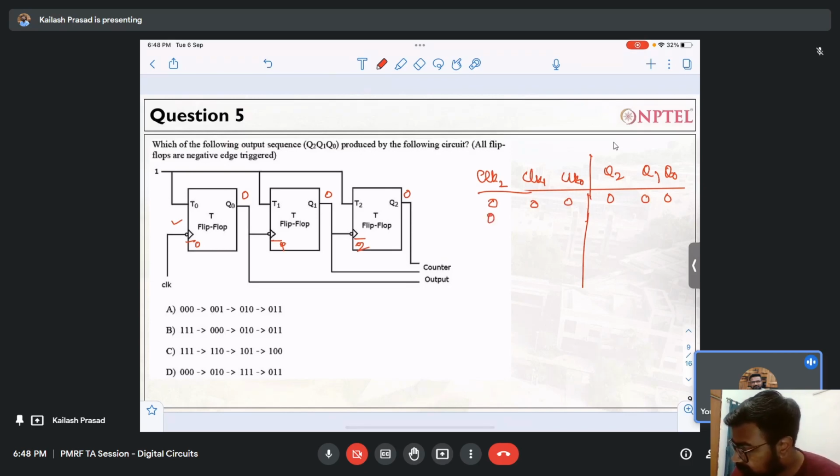It will go from 0 to 1, right? As soon as there is a rising transition which has come over here in this node, there won't be any change, because this won't be activated. This will be activated only if there is a falling transition. So the Q node will remain at 0, so no problem. So I have two cycles, but nothing happened.